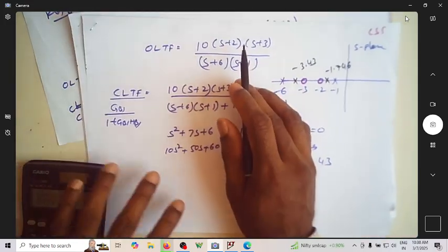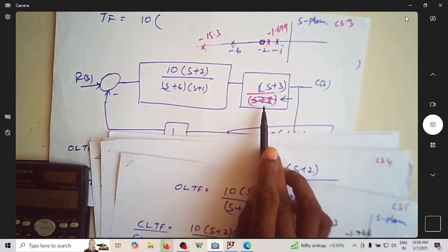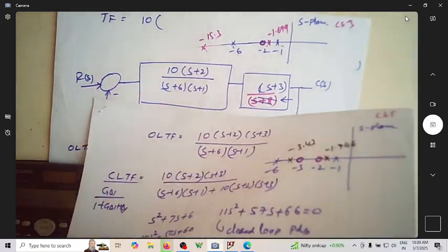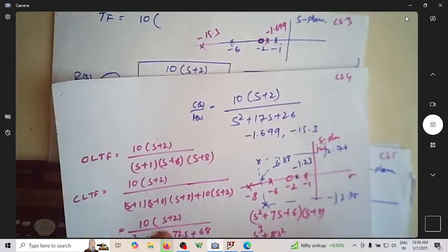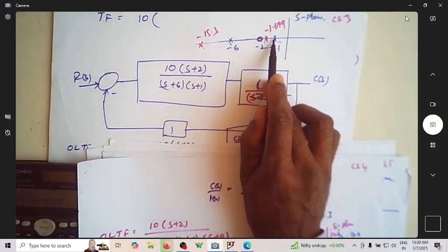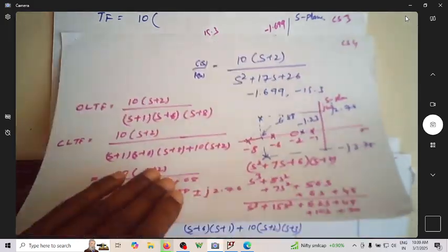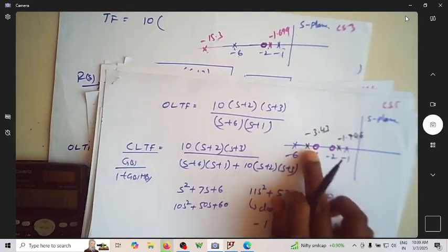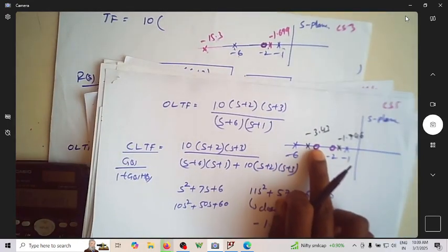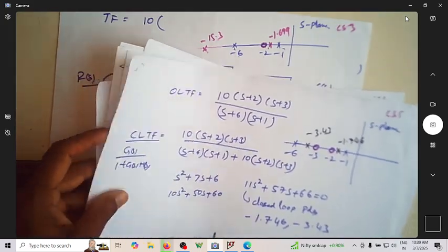In the previous case, when there was a pole added at minus 8, the poles were becoming complex. Do you see this? So this was becoming complex. When you didn't add anything, this is slightly moved here. This was actually going away. Now the moment when you added a zero, now it is going closer to this. Fine.